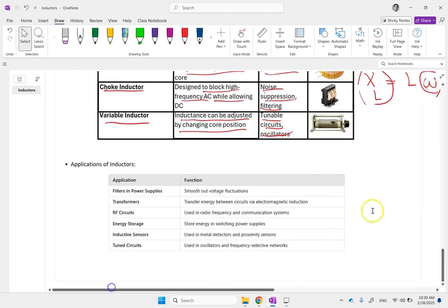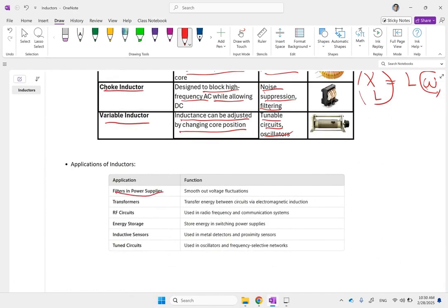And regarding their applications, as I mentioned, you can use them in power circuits to smoothen out voltage fluctuations because they act like inertia. Okay, L's are acting like inertia. In mass spring damper systems, they are similar to a mass. They make the system heavy, so you cannot easily change the current in it. They resist current changes, and of course the voltage changes as a result of that. Because they have inertia, they can transfer energy between circuits. They store energy in terms of magnetic field.